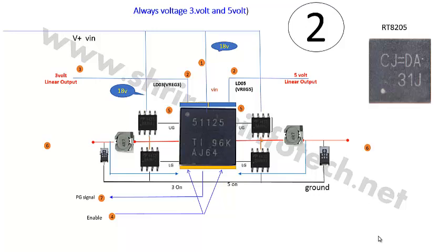So similarly, when power is there either from the adapter or from the battery, the SIO gets the power, and that power is 3 volt. In this section we are going to learn how this 3 volt is generated. On the screen you can see this concept diagram. I'll explain how this concept works, and then we'll go to the schematic diagram.